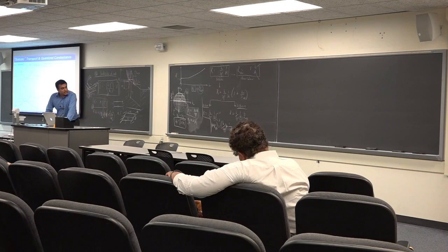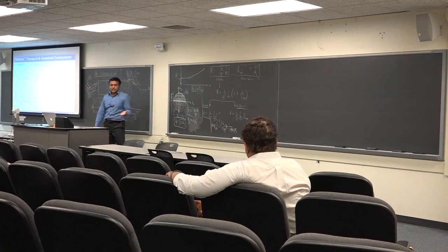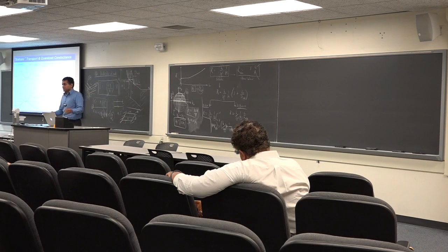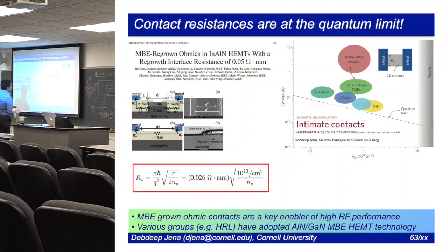And this used to be obviously just an academic exercise earlier, but nowadays it is a big problem, in some sense, because if you look at, just as an example, just as a summary, this is results from our research group working on gallium nitride, where we have a 2D electron gas. We essentially keep increasing the carrier density. And here's what I just derived.